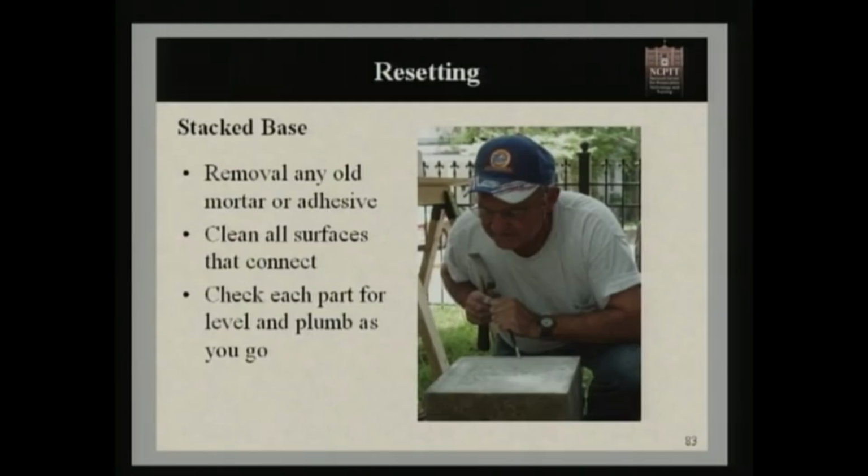And then we want to clean the entire stone, but paying particular attention to the surface that we've just cleaned the mortar from. A lot of times you have a very dry, dusty surface, and this is going to keep our new mortar from setting on it. And also a lot of biological growth has a tendency to build up in there, so we want to make sure to clean that off.